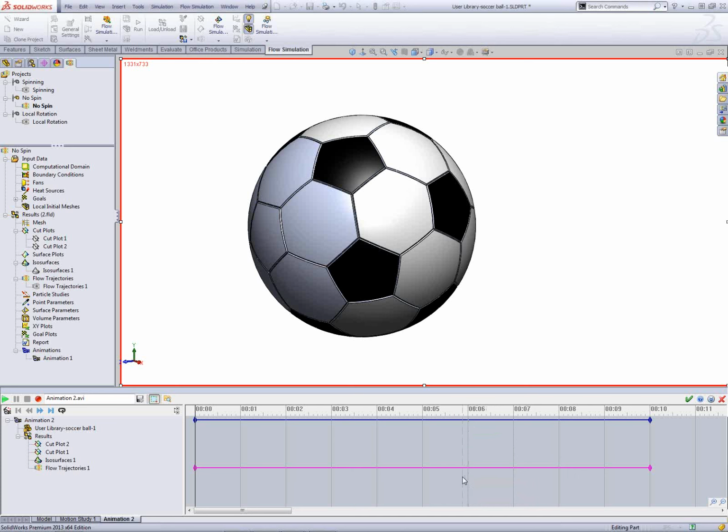So I left-click at the 10-second mark. And then the key here, to get this effect that we're looking for, is to go into the properties of this, and we're going to use this impulse mode for the properties of those trajectories. And I'm going to send that pulse of trajectories of spheres every 3 seconds.